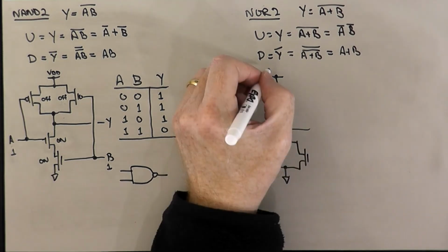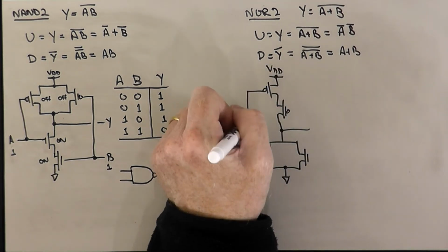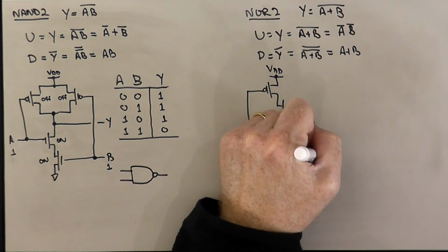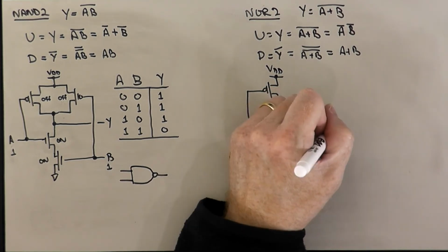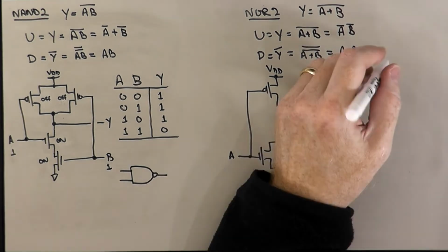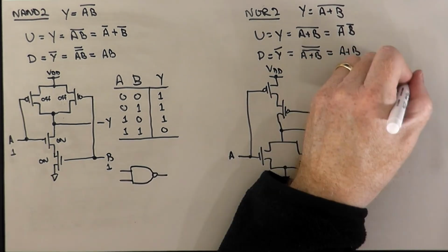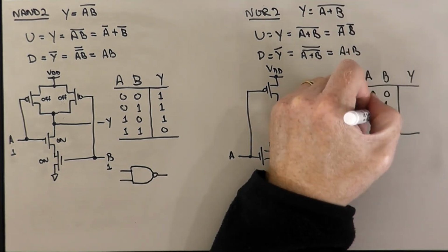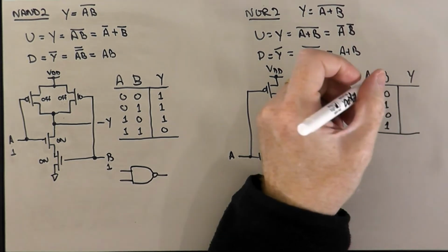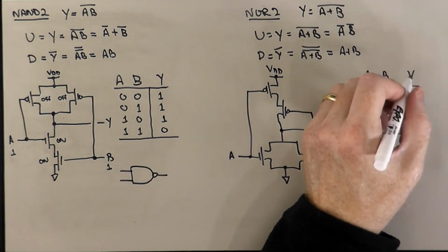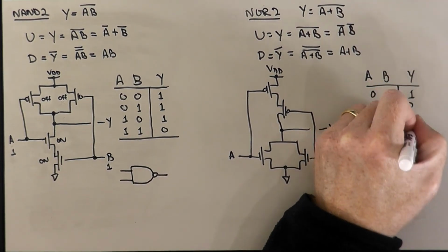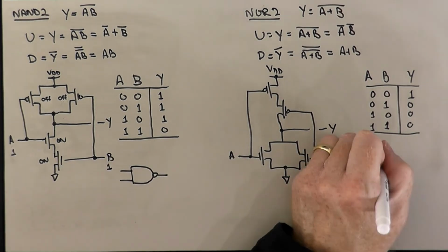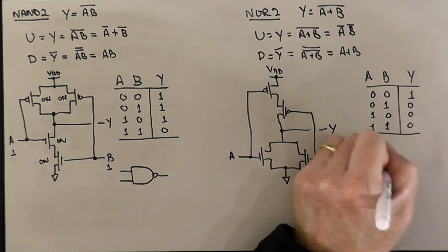It's the output of the gate. This is A. This is B. And this is the output of the gate Y. And so the truth table here for XOR gate, A B Y: 0 0 0 1 1 0 1 1. So XOR would be a 1 up here and 3 zeros here. And then the typical symbol we draw for a 2-input XOR gate looks something like this.